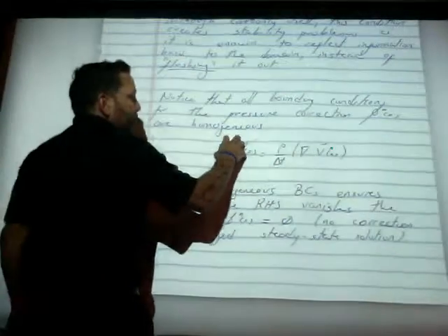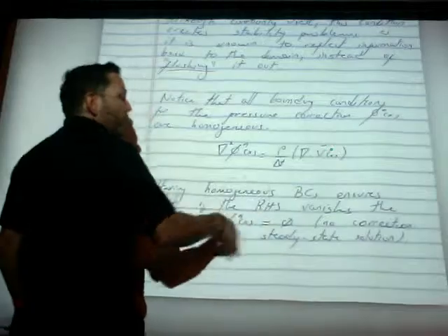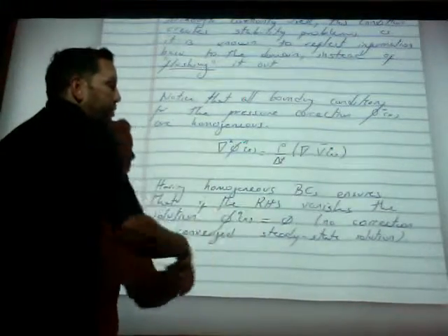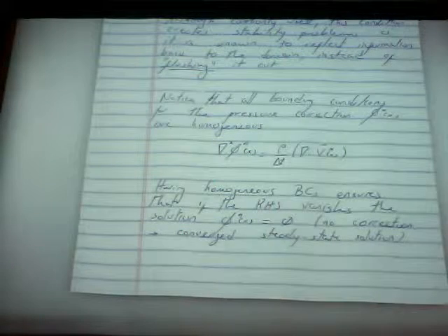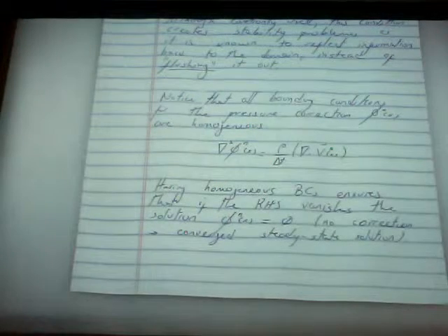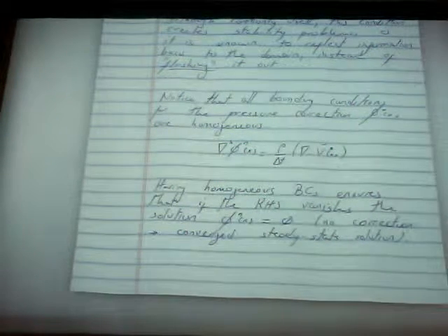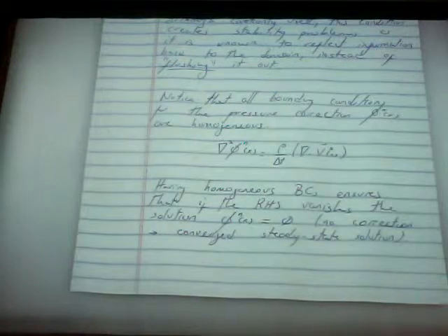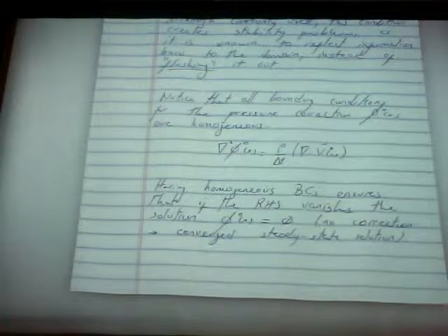If you have an equation that is equal to 0, the equation is homogeneous, and all boundary conditions are homogeneous, the solution is trivial. There's no pressure correction, you arrive at the final solution. So that's the argument to construct homogeneous boundary conditions for the phi problem.